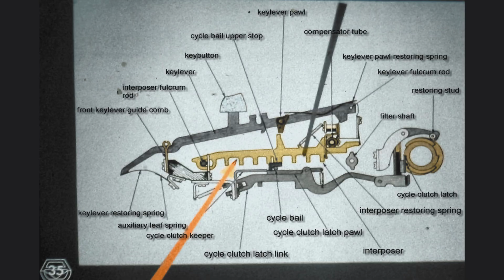Notice that this interposer comes equipped with all of its lugs underneath it. Not a single one is missing. This means that all positive selector latches and the -5 selector latch are going to be pulled forward. When all positive latches are pulled toward the front, there will not be any tilt or any positive rotate motion prior to the printing operation.